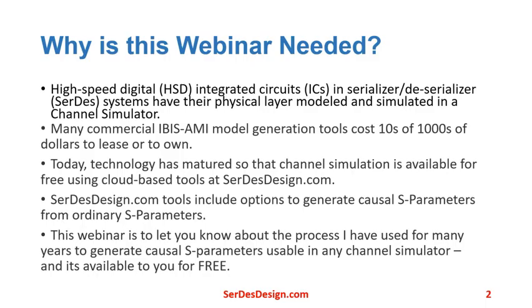Why is this webinar needed? High-speed digital integrated circuits and serializer-deserializer systems have their physical layer modeled and simulated in a channel simulator. Channel simulators are designed to use IBIS-AMI models that are based on the IBIS specification. Many commercial IBIS-AMI model generation tools cost tens of thousands of dollars to lease or own. Today, the SerDes channel simulation technology has matured so that it's available for free using cloud-based tools at SerDesDesign.com.